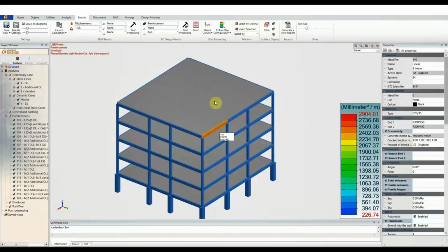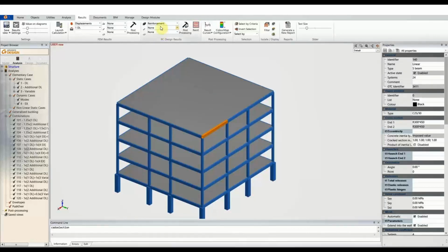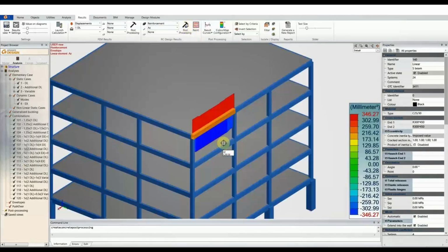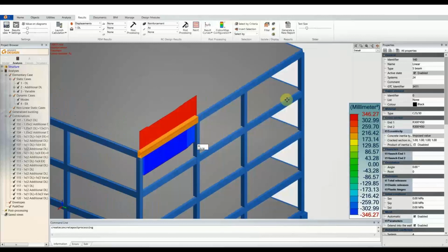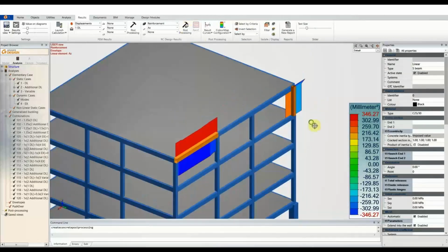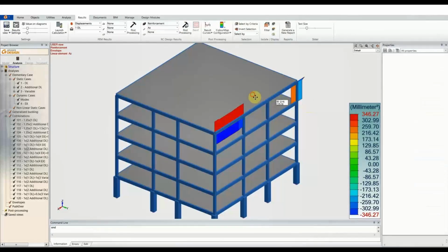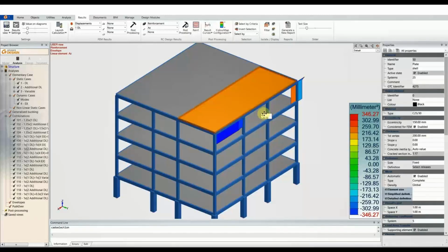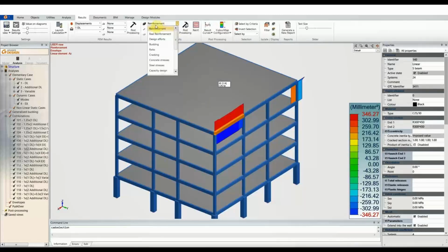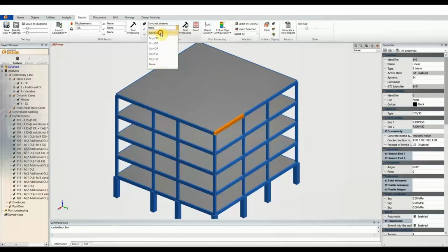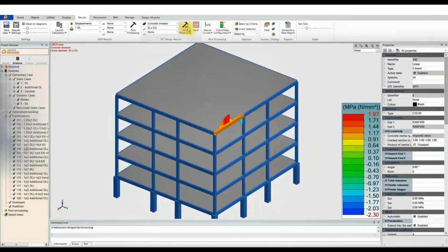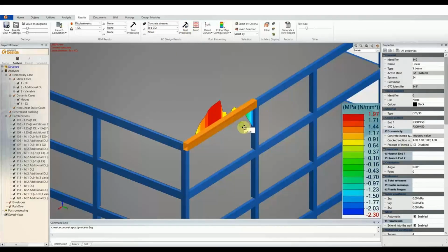Okay, so if we select now a beam as well, area of reinforcement in Z, so that is plus or minus 350. Okay, and what about columns? So we also have results for that. That's around the 200 mark, I'd say, 216-ish. Another type of result perhaps we could look at is the stresses. So the stresses in the concrete, relatively low there, 2 newtons a millimeter squared.